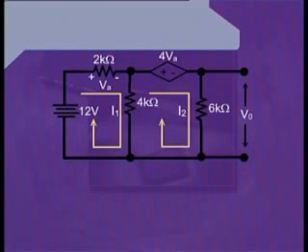From here we can write VA is equal to 2K I1. Now we have written 2K I1 because we have already assumed that current I1 is flowing through mesh 1, and VA has been already given by the question, that is the voltage drop across the 2 kilo ohm resistance.